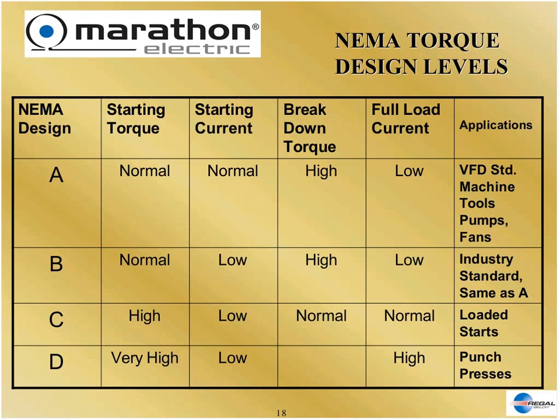So this is a little busy chart, but it just says, okay, here are the machines that use these design-type speed-torque curve profiles. The absolute standard is Design B. Those are general-purpose motors, and those are the ones that you normally find in most applications. A, C, and D are special. We won't get into it immediately, but just know that they are different because of the shape of their curve.